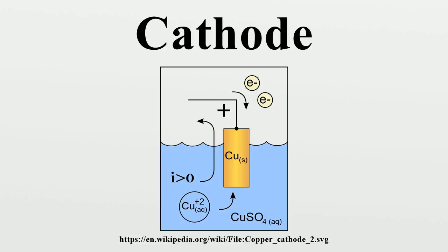In some devices the cathode is heated by the electron current flowing through it to a temperature at which thermionic emission occurs. For example, in some fluorescent tubes a momentary high voltage is applied to the electrodes to start the current through the tube. After starting, the electrodes are heated enough by the current to keep emitting electrons to sustain the discharge. Cold cathodes may also emit electrons by photoelectric emission.